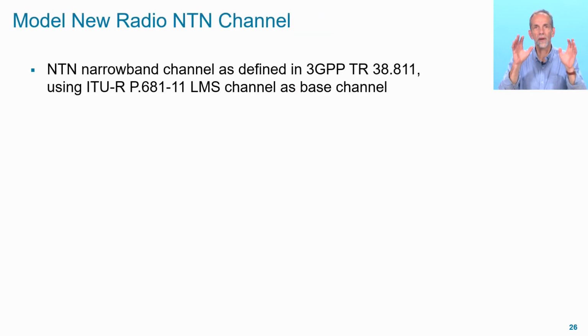Okay, there are times, though, when you have to get past the link budget and actually start modeling an IQ waveform. The first thing you have to consider is how to model an NTN channel, and this was done by 3GPP all the way back in 2018 with Release 15. An NTN offers 3 different channel models as specified by 3GPP.